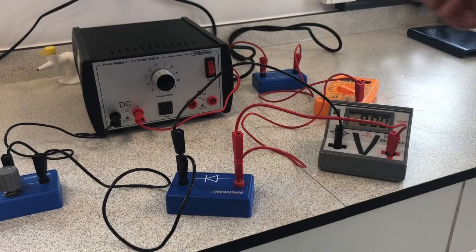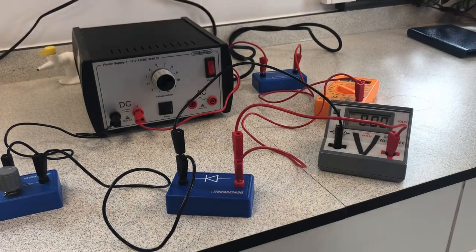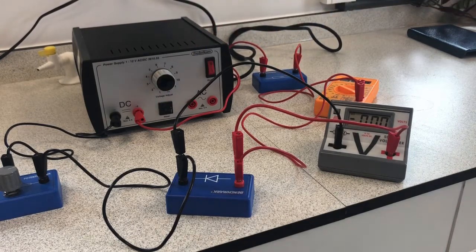So again, we've got the power supply connected in series to the resistor, the milliammeter, the diode, and the variable resistor and back to the power, and we have the voltmeter in parallel over the diode. We're going to do exactly the same with this setup. Turn the power on, take our readings, alter the variable resistor and get a range of different results. We're then going to switch the power supply to run in reverse and again get a range of results.